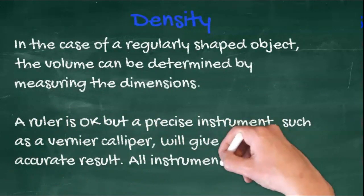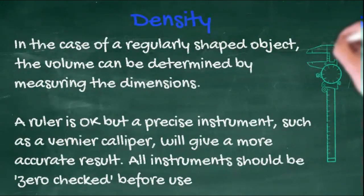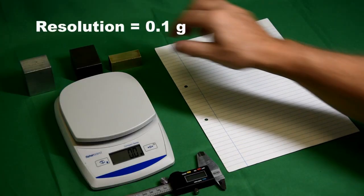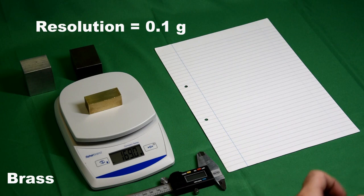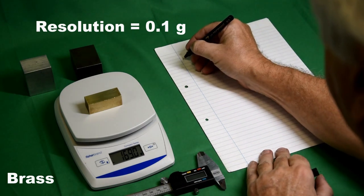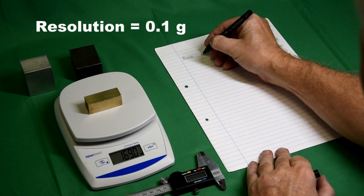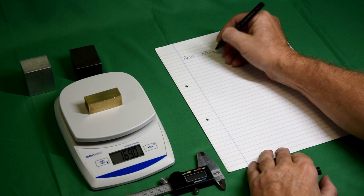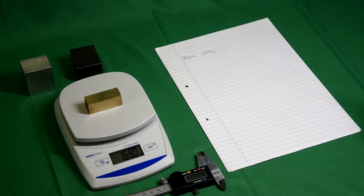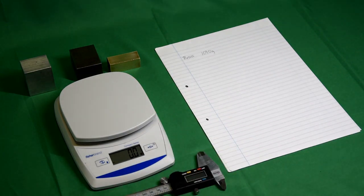A ruler is okay for this, but a more precise instrument, such as a vernier caliper, will give a more accurate result. All digital instruments should be zero-checked before use, and this balance has a resolution of 0.1 grams. Starting with a brass block of a mass 169 grams. Don't forget to zero check.